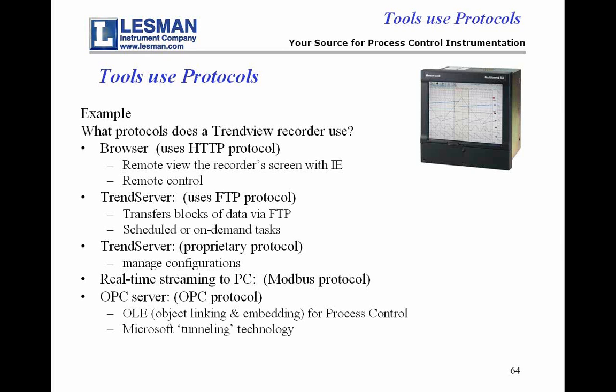When the recorder has to transfer blocks of information to the software, it uses the file transfer protocol, the FTP protocol. When you need to change a configuration using the software, there's some proprietary protocol that does that. I don't even know what the name is. It just works. There's a mode where the data can be streamed real time from the recorder to the PC, and that uses the Modbus protocol.